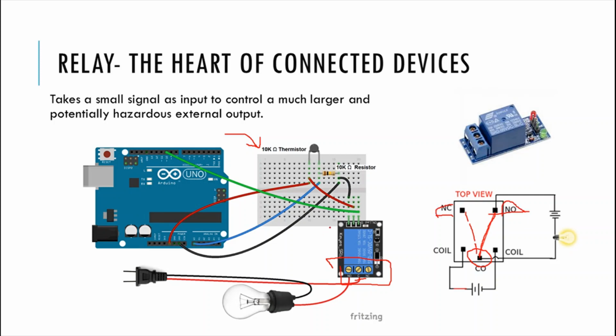Now on the other side, there are generally between 2 to 3 pins. Most relays that come out these days use 3 pins here, and one of them is the signal, one of them is 5 volts, and one of them is the ground. Now the arrangement of these may vary based upon the manufacturer, but these are generally the 3 pins that exist on this sugar cube relay.